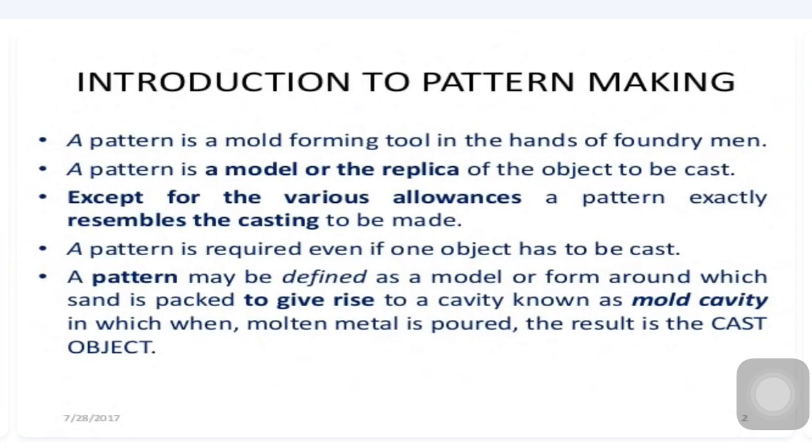So a pattern may be defined. If someone asks you to define the word pattern, you need to describe this word in a very detailed manner. So a pattern may be defined as a model or form around which sand is to be packed, to give rise to the cavity known as a mold cavity, in which when the molten metal is poured, the result is the cast object.